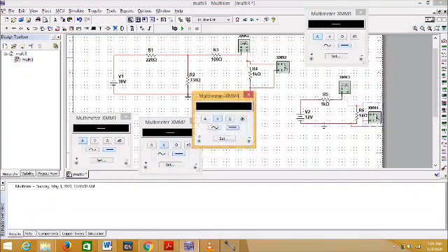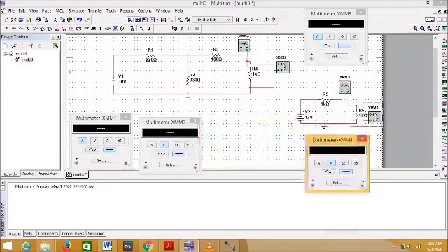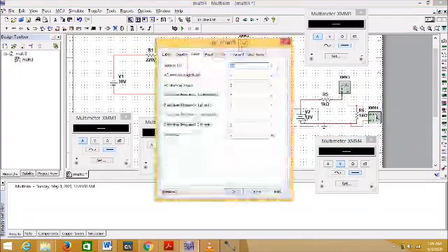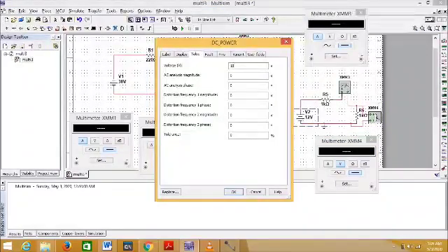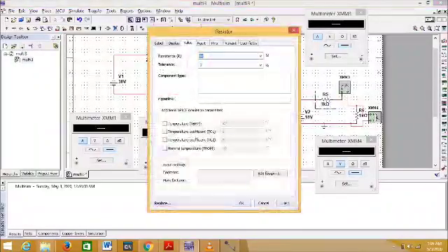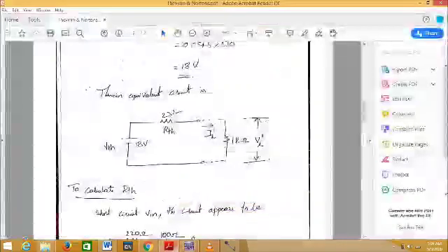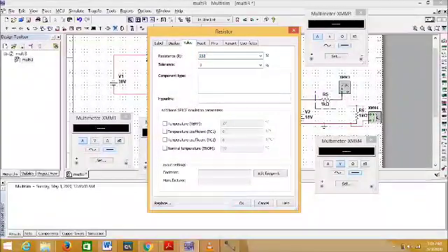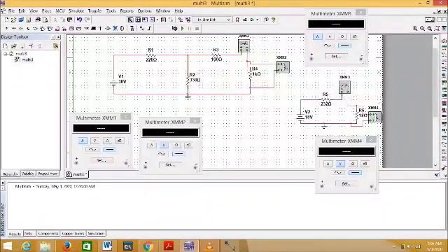So connections were over, so this should be voltage. Okay, these two windows correspond to this Thevenin equivalent circuit. I need to change this RTH also. What is the value of VTH? VTH is 18. Okay, Thevenin equivalent voltage, and RTH is, what is RTH? Right, it is 232 ohms. Okay. Right, that's all.